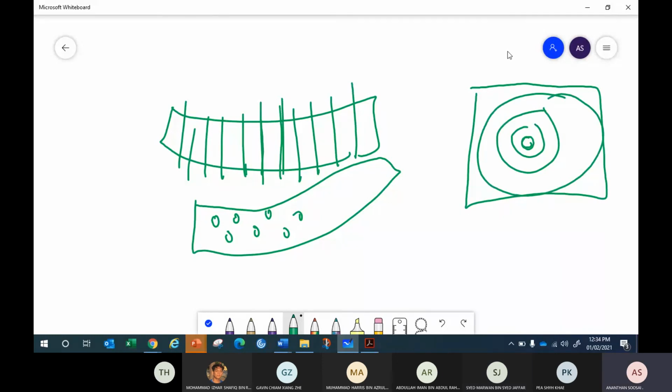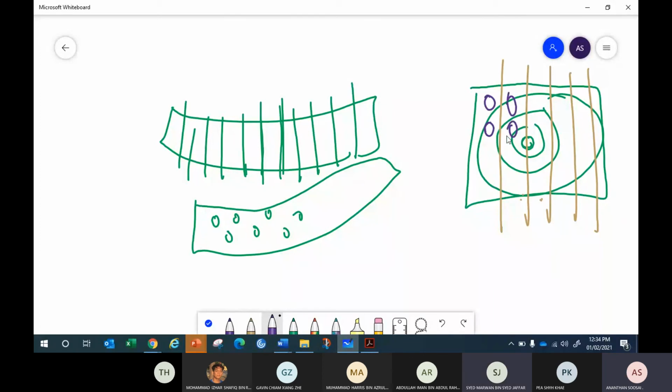But if you put an insulator in between, the big circle won't happen. Why won't it happen? Electrons cannot pass the insulator. So now how is the eddy current going to flow? Eddy current only makes a small circle. It cannot make a big circle. It's stuck because it cannot pass the insulator. So it makes a small circle. So that means, do you have eddy current?